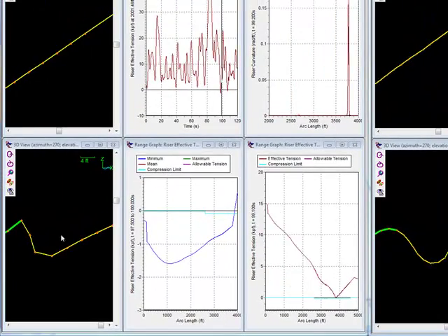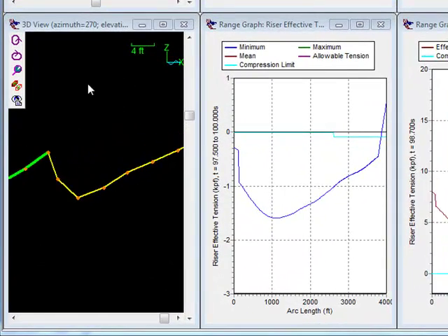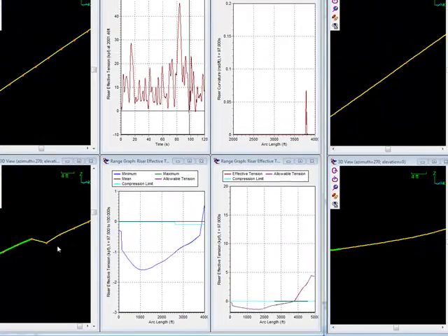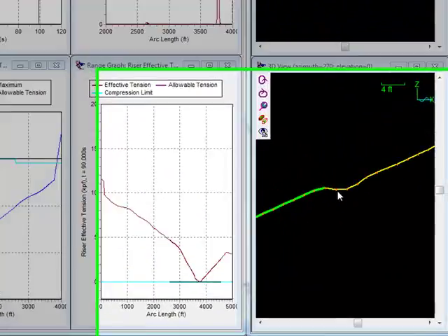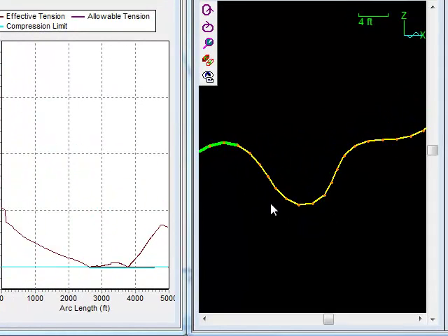And over here we see the typical segmentation that we used for most of the runs, where the element length is about 5 feet. The behavior we see here is similar in nature, but now we need to quantify whether its magnitude is such that we're being misled, because there are not many elements that make up these bends, whereas in this picture there are quite a few elements making up each of these bends in the wave shapes.